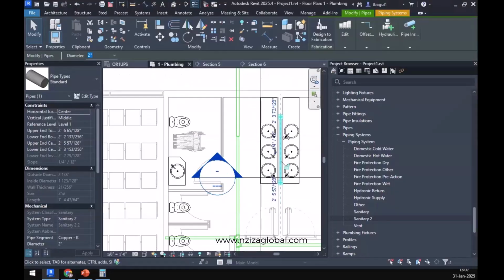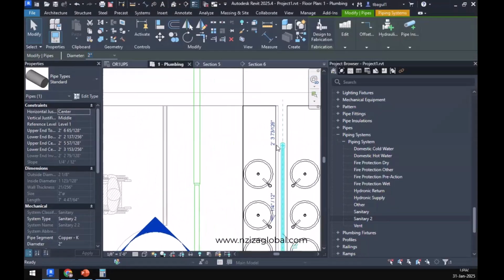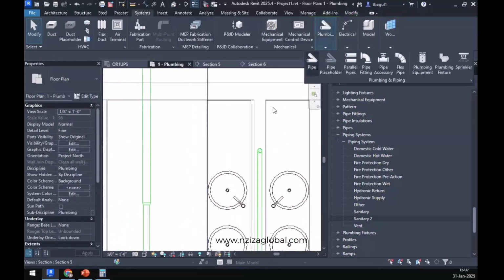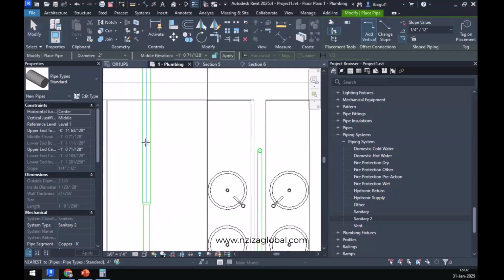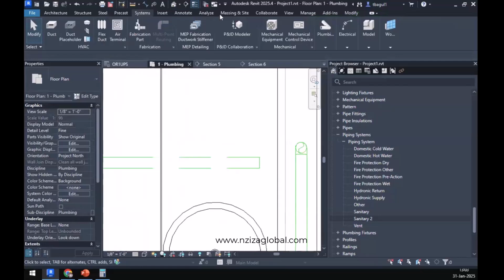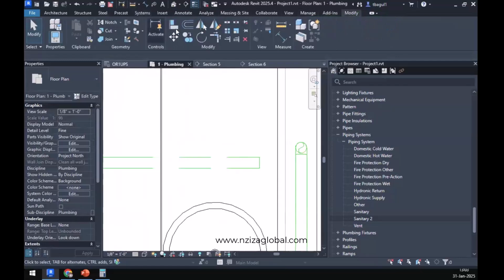Now, talking about the pipes, now it drops down over here. Again, we need to connect the pipe. It is a 2-inch pipe and it needs to be connected over here. All right. Again, I will inherit elevation. I will slope it up to this point. All right. I'll make sure that the pipes are properly aligned. So modify, align tool over here. It is with this point that we need to align our pipe. Looks like the pipe, what happened?